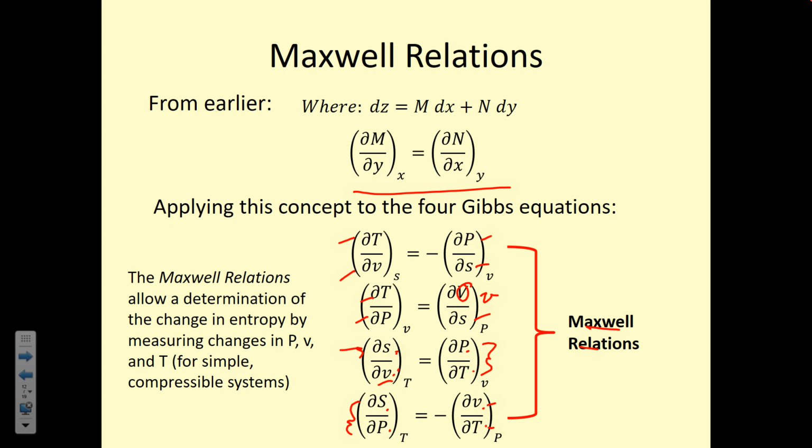So that's a very important concept that I want you guys to really think about and remember in future homeworks and quizzes, exams, whatever comes up in the future, to know that not only do you have to calculate the actual enthalpy, which on problem 3 a lot of people missed too, you would have to calculate an actual entropy, an actual temperature, an actual internal energy, an actual specific volume. All of those quantities are going to be changing. The one thing that probably won't change is pressure. But all of these other quantities will change at the actual state.